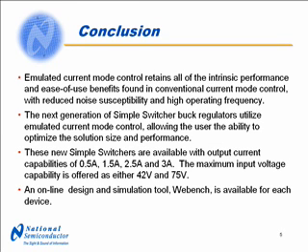This concludes my presentation. Emulated current mode control retains all of the intrinsic performance and ease of use benefits found in conventional current mode control with reduced noise susceptibility and high operating frequency. The next generation of simple switcher buck regulators utilizes this emulated current mode control, allowing the user the ability to optimize the size and performance of their solution.